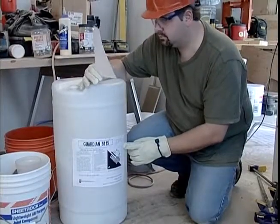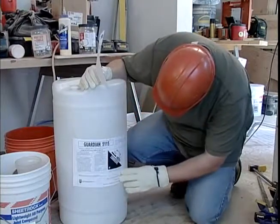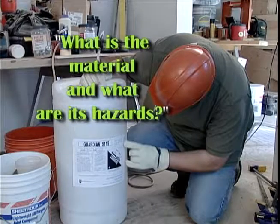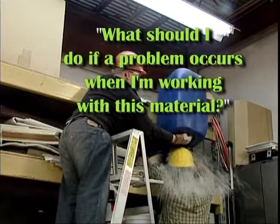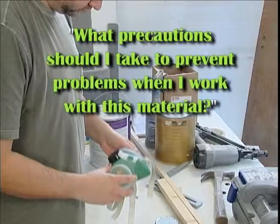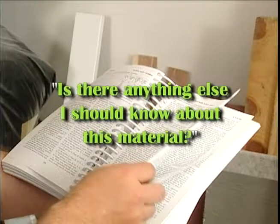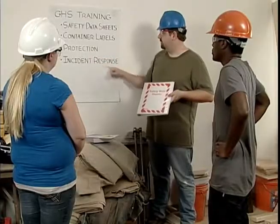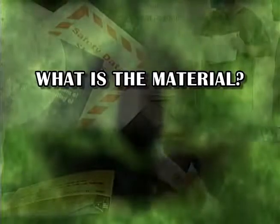Safety data sheets are designed to answer 4 basic questions that anyone who encounters a chemical might have. What is the material and what are its hazards? What should I do if a problem occurs when I'm working with this material? What precautions should I take to prevent problems when I work with this material? And finally, is there anything else I should know about this material? Each of these questions is answered by one or more sections of the safety data sheet. For example, sections 1, 2, and 3 provide answers to the first question: what is the material and what are its hazards?